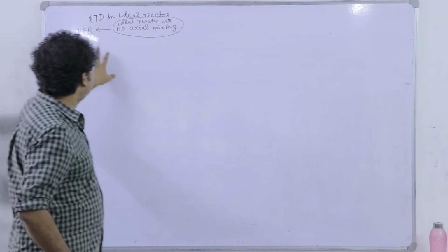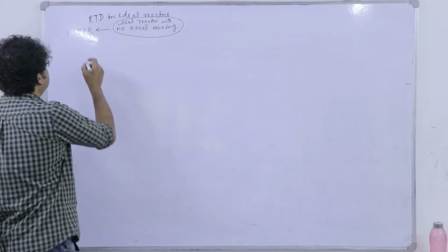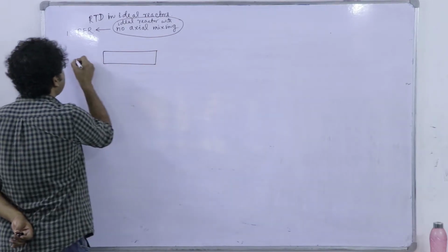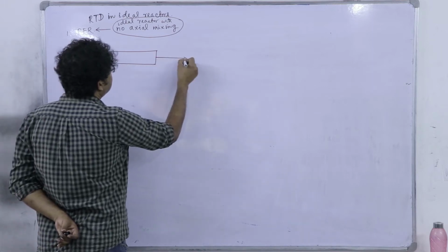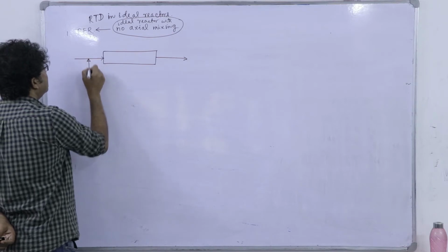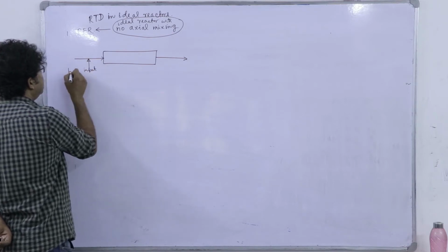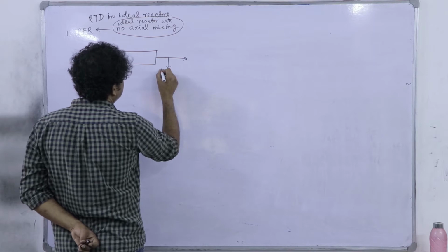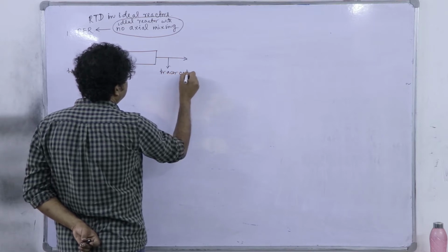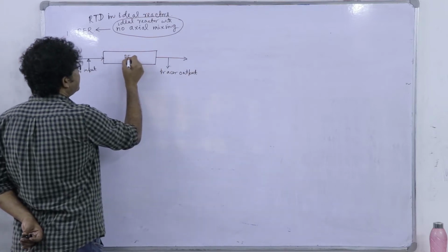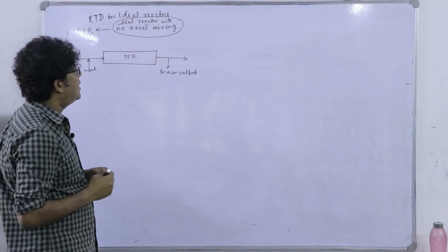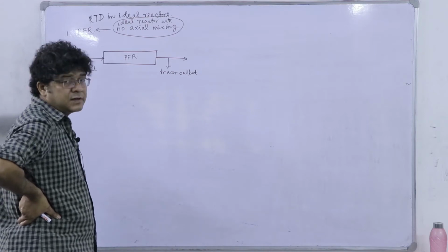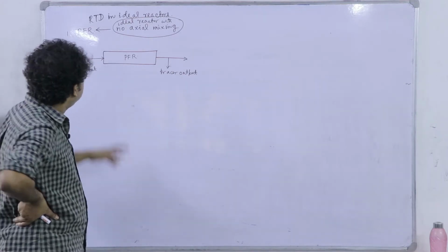If I am using a pulse, its idealization is the Dirac delta function. So, think I have a reactor, and here is the tracer input, and from here we are analyzing the output concentration, the tracer output, and it is a PFR. As we do not have any PFR in real life, we have to derive the expressions of the RTD curves, mostly the E curve, conceptually.